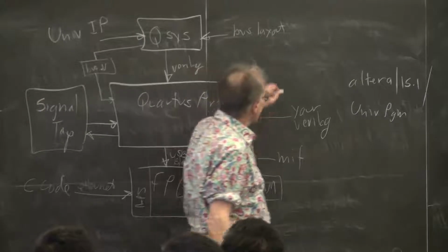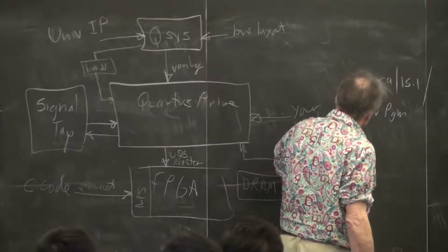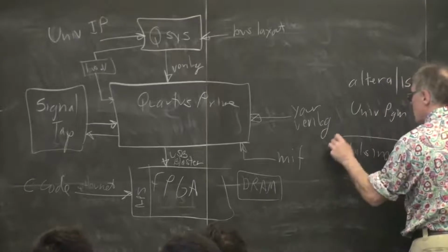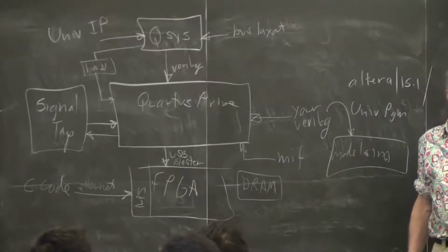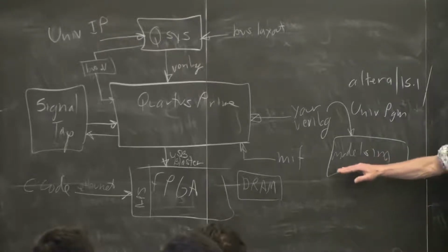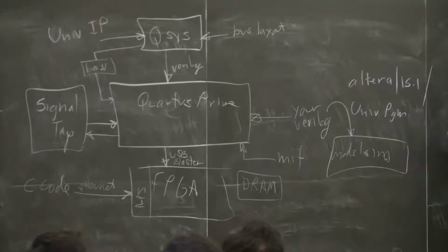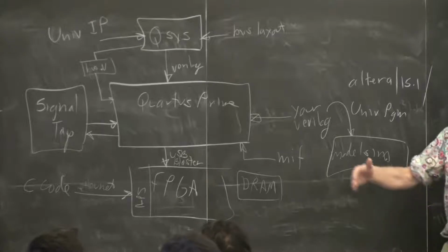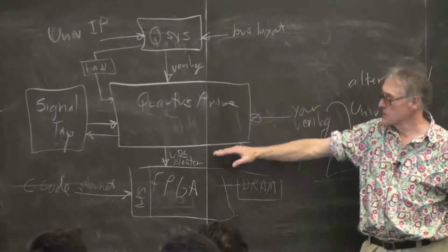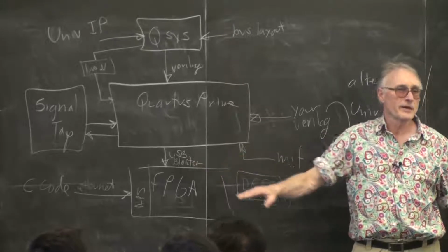You can take your Verilog, put it over into ModelSim, write a test bench for it, and simulate it. You're going to find that's very useful for compute modules, like for instance in Lab 2, when you have to build a simulated analog computer on the FPGA fabric. You're probably going to want to simulate it before you connect it to a bus master, where you have to then compile it through Qsys and Qsys Prime, and 15 minutes later you can find out it doesn't work.